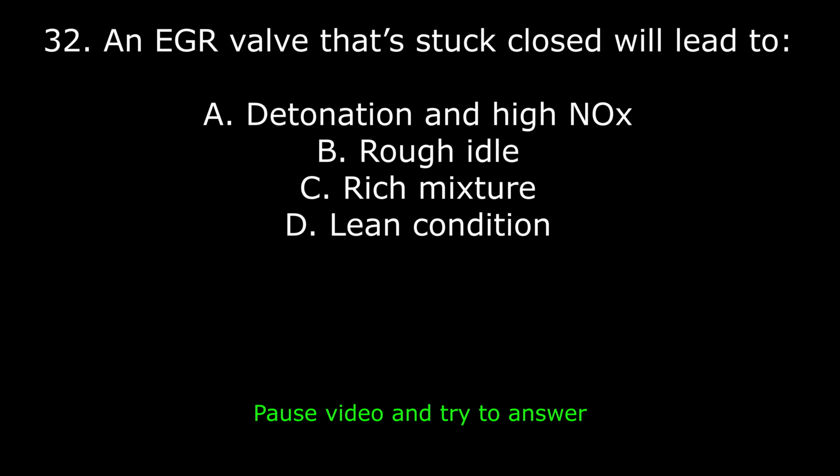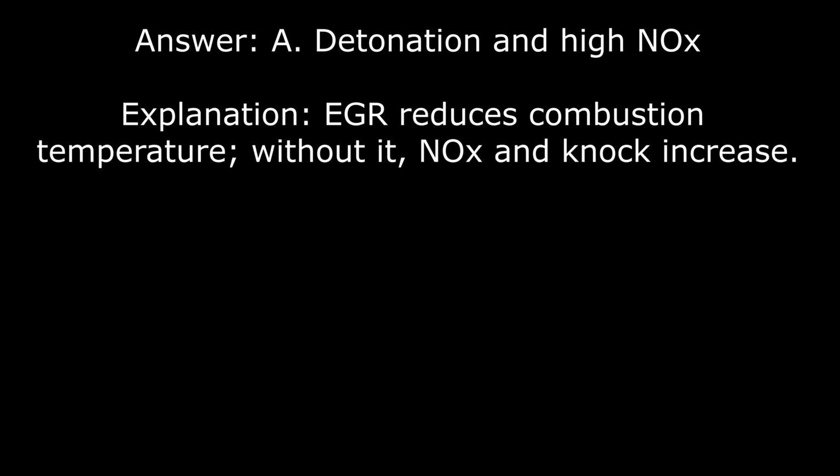32. An EGR valve that's stuck closed will lead to A. Detonation and high NOx, B. Rough idle, C. Rich mixture, D. Lean condition. Answer: A. Detonation and high NOx. Explanation: EGR reduces combustion temperature. Without it, NOx increases.